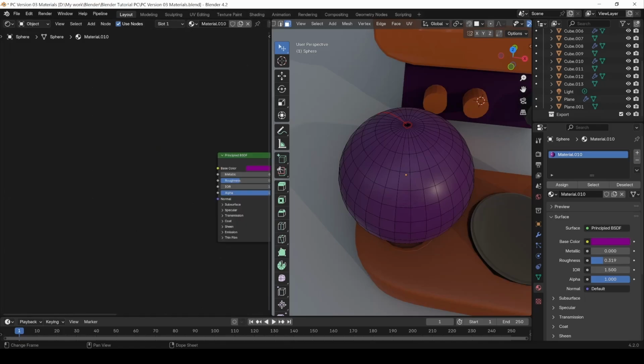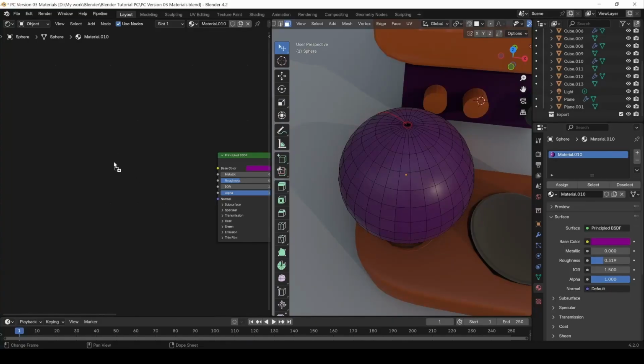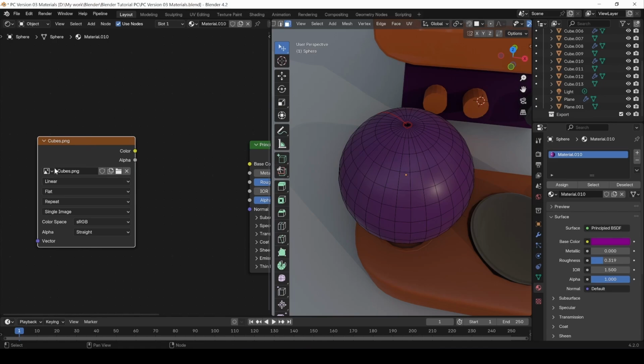Now let's go to this. Let's actually go to this. Here it is, and open it in Blender like that. Just release here. Now we have that cube assigned to this texture image. Okay, now you can see this texture image, as we said before. Here is the name. Here are other elements that are already in our Blender project, like the checker, and now we added this cube, so now even this is here. This is to assign a fake user if you are not using this, to duplicate it, and this to open a new one, and this is to delete it.